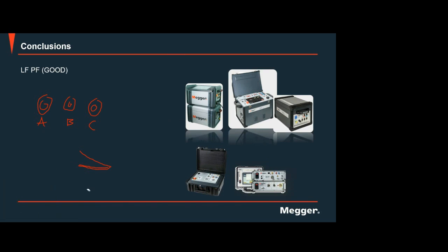All right. And the third question is, what is the difference between AC and DC insulation tests? Oh, okay. That is a good one because, previously, maybe some of you will say, I already have an insulation tester, a DC insulation tester, and this is already good, right? But we have two methods for insulation testing. We have the DC method, which is our insulation resistance. Of course, Megger is well known for this one. We have the Megger insulation testing.